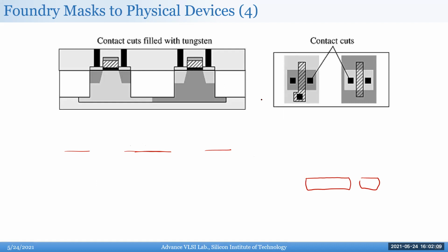And then obviously you need to make contacts to the top layer. So you do these holes, and typically this is tungsten. The reason they use tungsten is, again, a processing thing. If you did aluminum or whatever it is, with holes, it will not seep in, so you get very high resistive contacts. So tungsten works better. But now with higher end processes, the metallization is copper, as well as the vias, which is much more conductive. Process-wise, for low cost processes, it's difficult to do with copper, because it oxidizes with silicon dioxide.